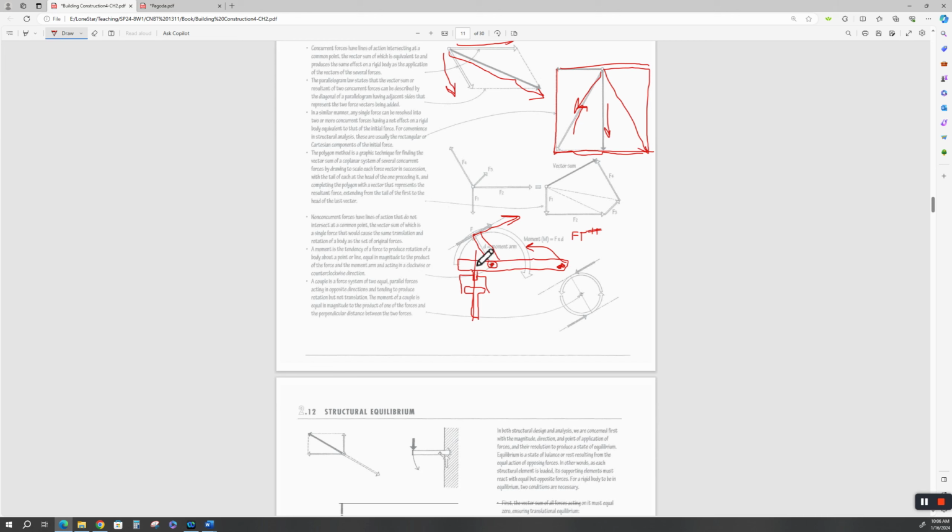So let's say this was 1 foot. And you're putting 10 pounds of force on the end of the wrench. Then you've got 10 foot-pounds, right? If this was 2 feet, it'd be 20 foot-pounds. Or if it's in inches, then you could do it in inch-pounds. So foot-pounds or inch-pounds. And you might talk to your structural engineer, and they might be saying, well, okay, if it's a structural steel frame, then we're going to have so many foot-pounds of torque on the bolts to erect the structure. But that's a moment. And that's the overturning thing.